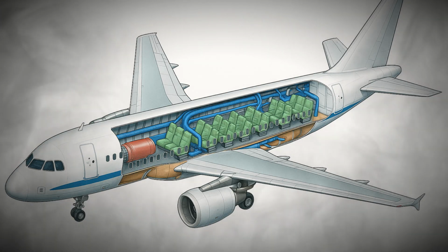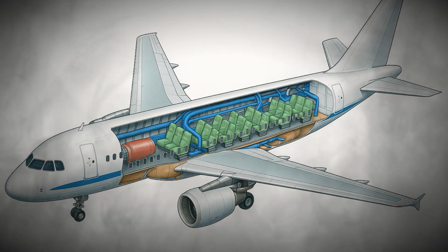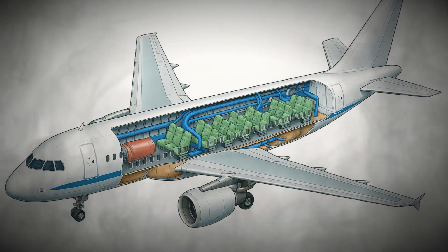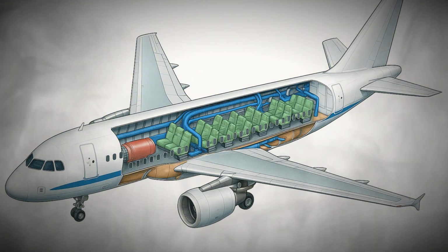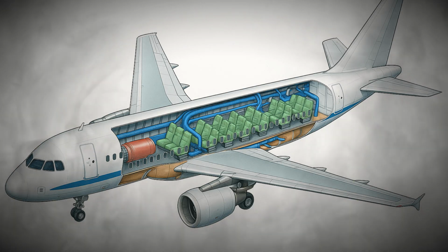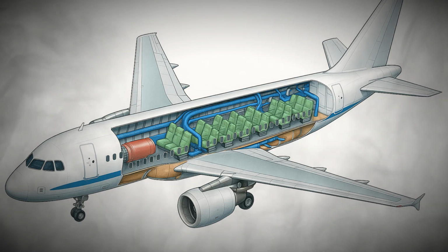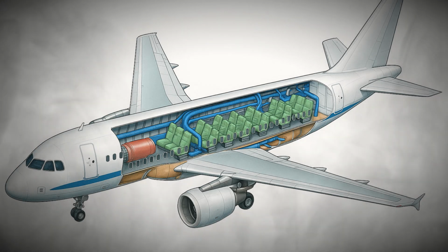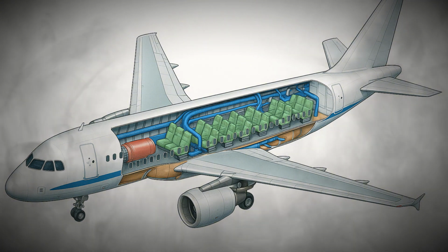However, too much stability can make an airplane sluggish and difficult to maneuver, so designers must strike a balance between stability and responsiveness. Fighter jets, for example, are often designed with less inherent stability to make them more agile, relying on computer systems to assist pilots with constant adjustments. Airliners, on the other hand, prioritize strong stability to ensure passenger comfort and efficient long-distance travel.